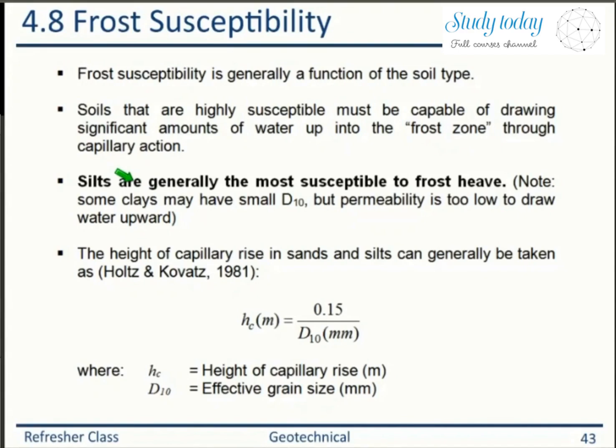Therefore, if you happen to have your structural fill over the water table, then you can draw a lot of water from the water table and bring it into the silt, and when it becomes winter conditions, the ground is frozen. When the ground is frozen, water freezes to ice, and if that silt is bearing your building, the building will be heaved. So to prevent that heaving action, you have to be careful not to use the silt, right?